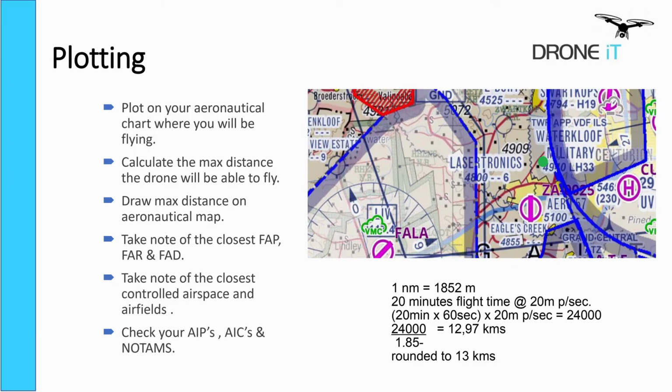More or less how you can do this is to calculate distance. Distance is time times the speed of the drone. This will give you the max distance that the drone can achieve in ATTI mode. The reason we do this is to see, in case of a flyaway, more or less where the drone can end up and what the risks might be in that surrounding area.